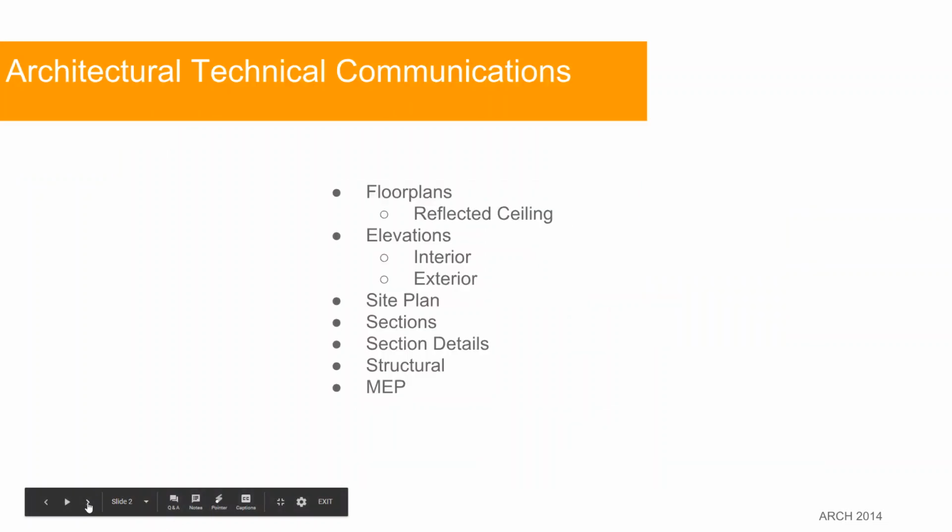So I've created just a brief list here about the kind of drawings, and I wanted to show you some slides so you have some visual examples of what these are. Floor plans, I think we're all familiar with. A reflected ceiling is a view similar to the floor plan, but as if you were looking in a mirror, a reflected view of it, looking down at the floor, seeing the ceiling. Elevations, interior, exterior, the eye level perspective looking at your building.